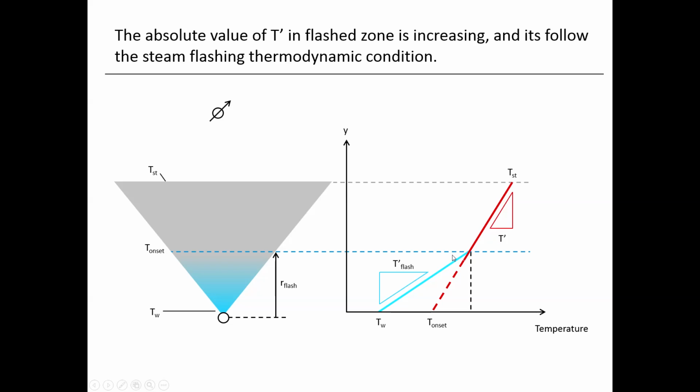But there is another temperature gradient, which we call the temperature gradient of the flash zone. This temperature gradient is based on a lot of parameters: the pressure at the drawdown, pressure at the chamber, permeability, the subcool, a lot of things. Based on that, you calculate the PVT flashing, and then you come up with this temperature gradient.